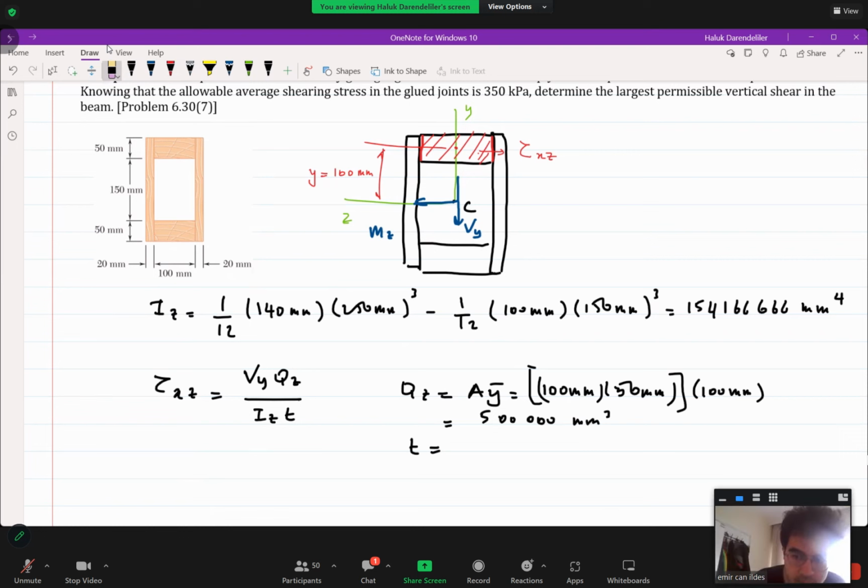Exactly. It is 2 times 50, being different than the previous problems. Look, it is 2 times 50 millimeters. Why? Because to remove this cross-hatched area from the remaining, we have to cut the piece, by an imaginary way, not only with this length, we also have to do this. Is this clear? So T is 50 millimeters here and 50 millimeters here.